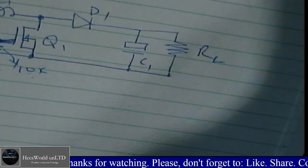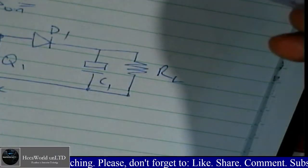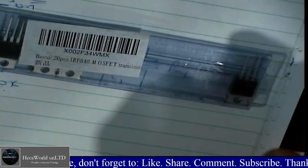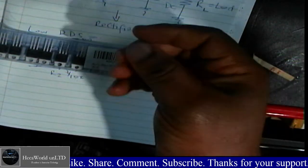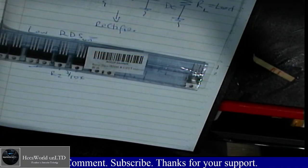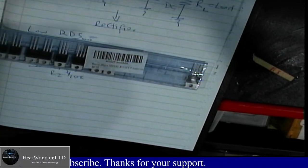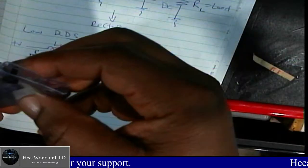The next thing is to fire up the soldering iron. So I'm gonna get out one MOSFET, but before I touch the MOSFET by hand, I'm gonna try to discharge any static electricity on my palm by touching heavy metal. My workstation is made mostly of metal, so I'm just going to touch it to discharge any static charges, especially in the cold. This is a winter season, so touch metals to discharge your fingers. And then I'm just going to open and take one of the MOSFETs out.